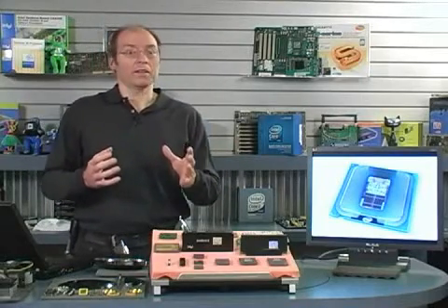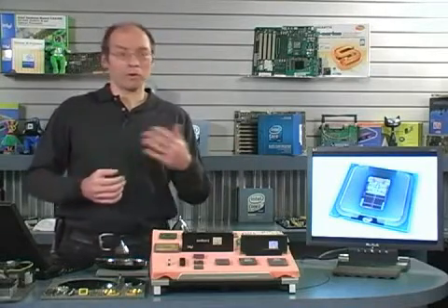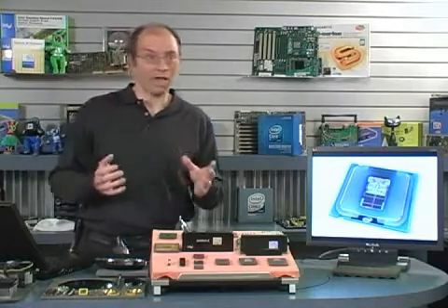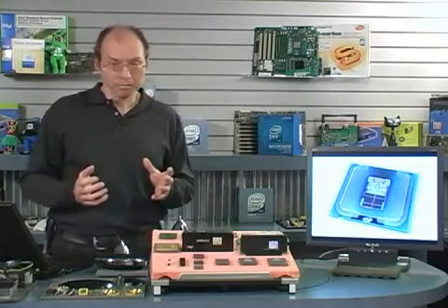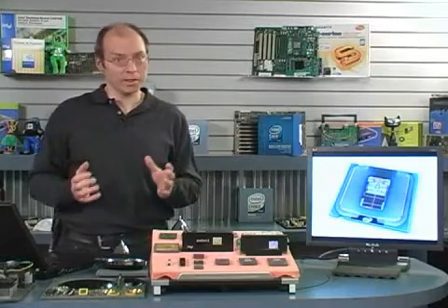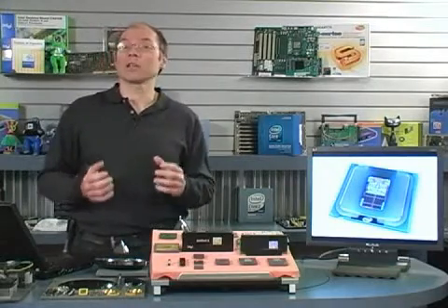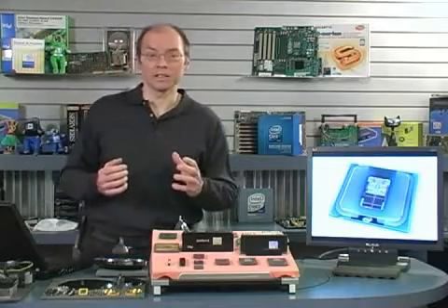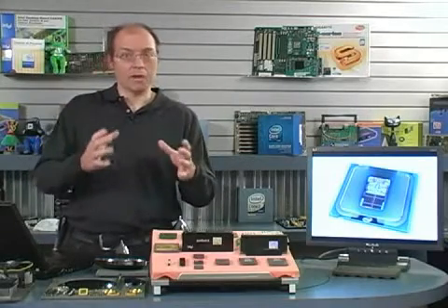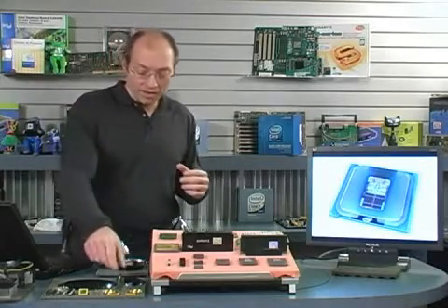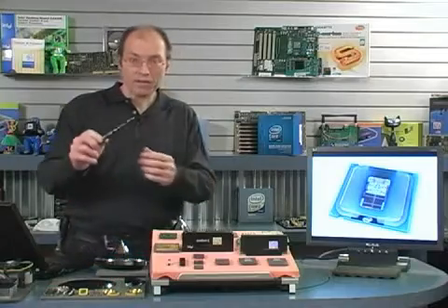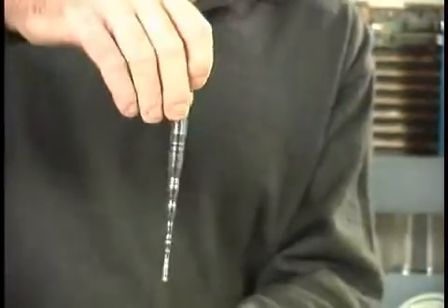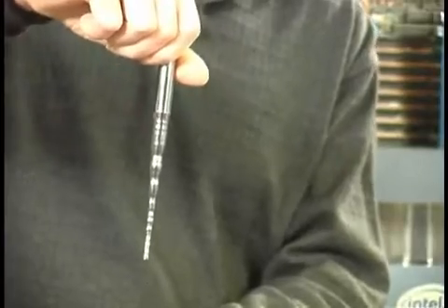So what happens is we take the sand, melt it down, and put it through a purification process until we extract 99.999% pure silicon. Now, even that's still not ready to make chips out of. We need the silicon not only to be pure, but to be in the form of a crystal. So the pure silicon is melted in a vat, and a seed crystal, like the one I have here, is dunked into the vat of molten material. It's slowly turned and then pulled out.